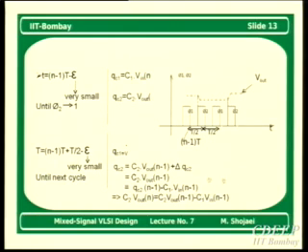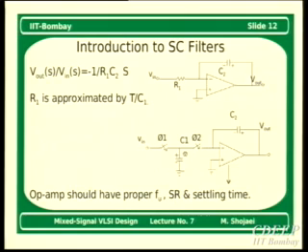Therefore, you need just to write the equations, and the way equations are written is always we look at the charge redistribution between capacitors. Considering the op-amp is almost ideal and the amount of input current is almost 0, we don't have any current which flows through the input capacitance of the op-amp, meaning it's almost negligible.